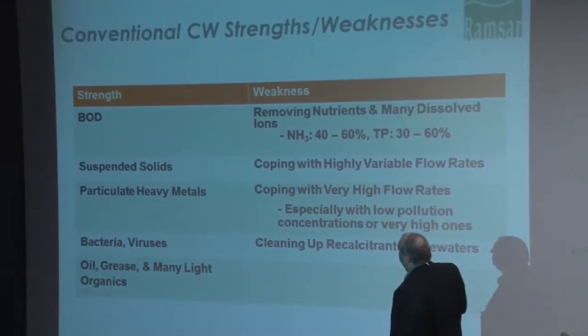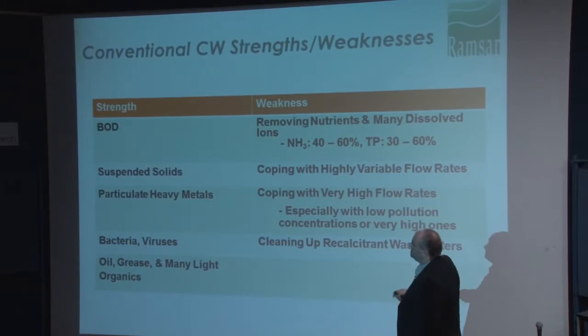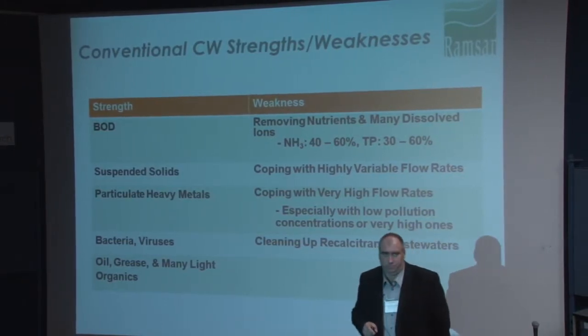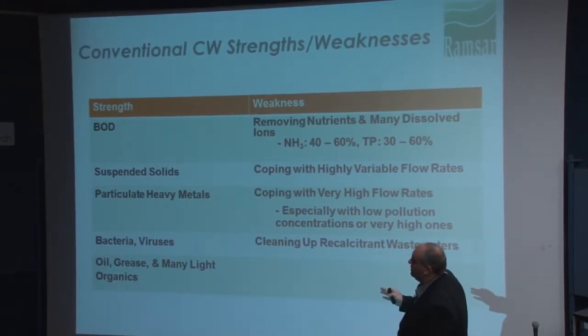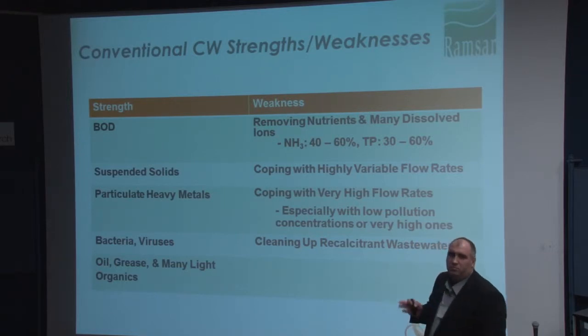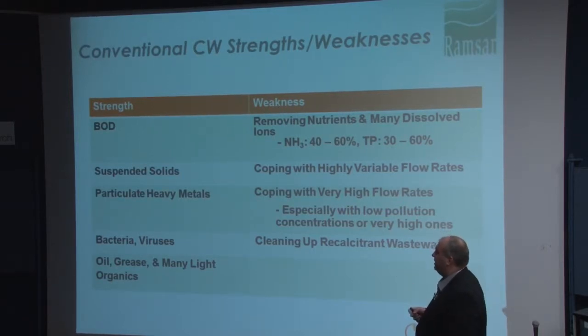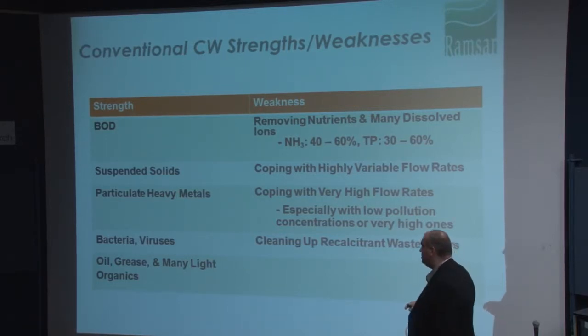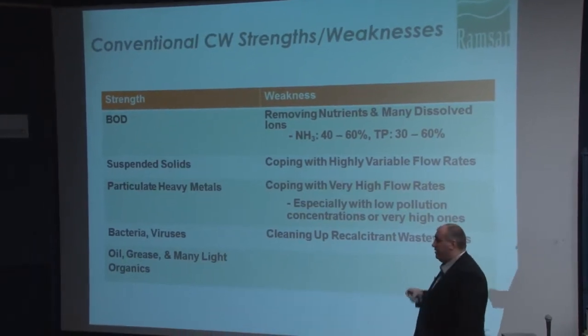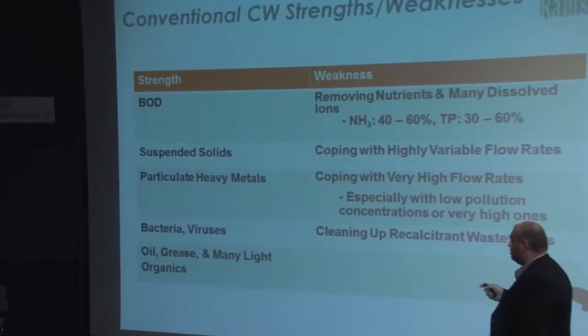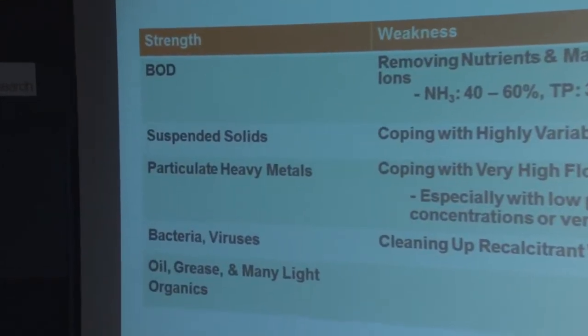So conventional constructed wetland strengths and weaknesses. Constructed wetlands are great at removing biochemical oxygen demand. They do quite well at reducing suspended solids concentrations, particulate heavy metals, bacteria, viruses, oils, grease, and many light organics.